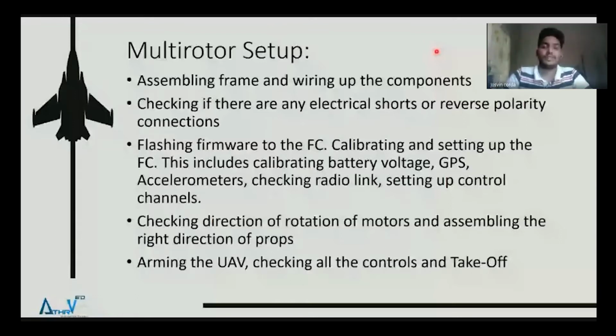Then you have to calibrate the battery voltage. This is mainly done to give a warning to the pilot as to what is the battery level, the battery percentage available of the aircraft. Then you have to calibrate the GPS, accelerometers, and check the radio link.